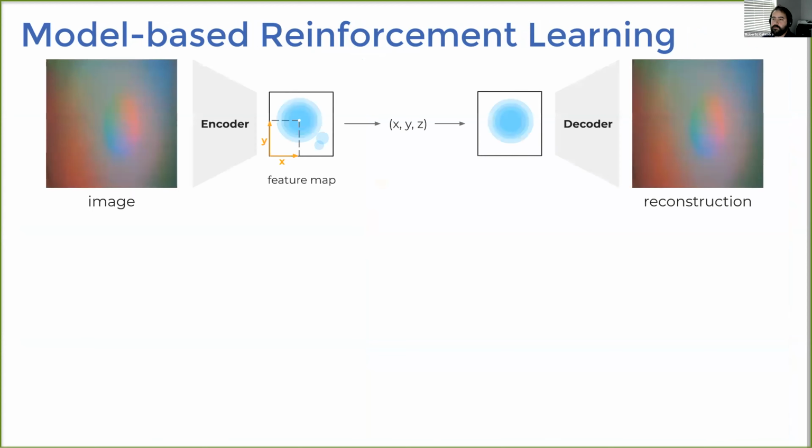So the dynamics model is learned in a two-stage fashion from raw tactile inputs, where we first learn an autoencoder network with structural bottlenecks that essentially extract the XY position of the marble plus the amount of force being applied to the marble.